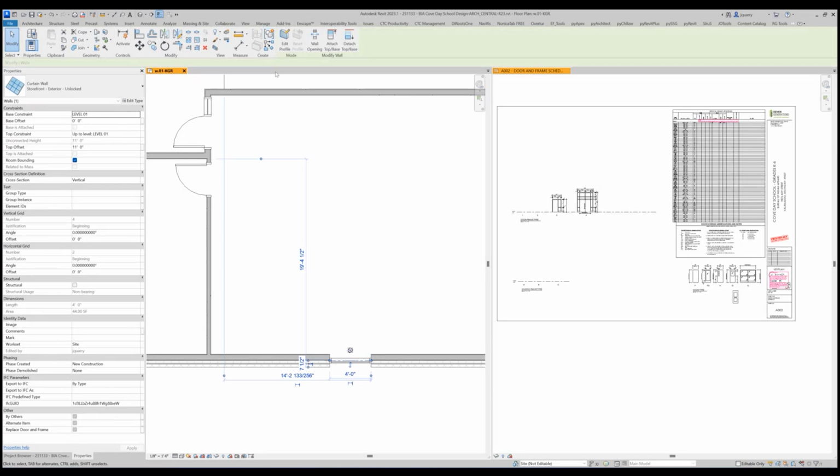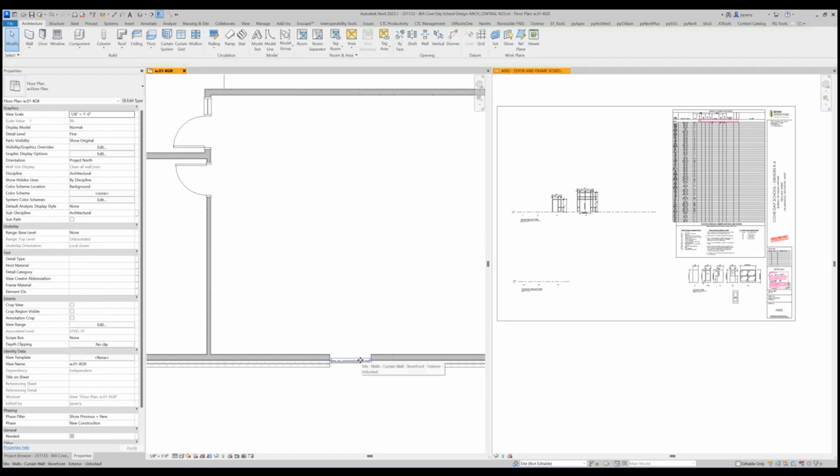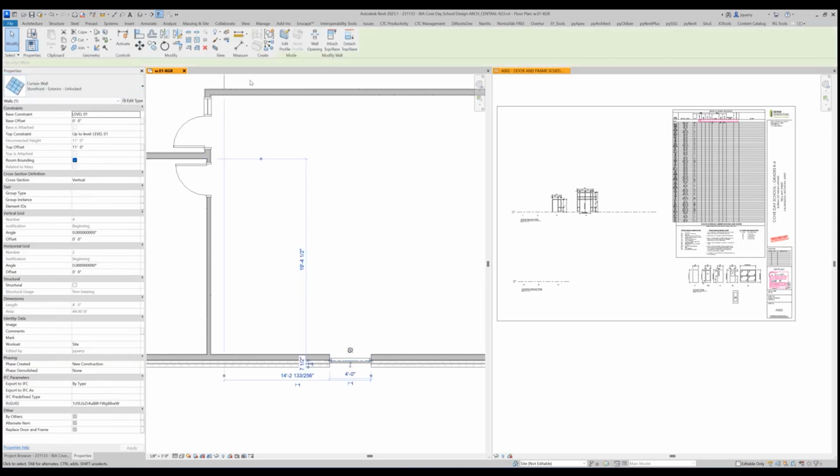Did you hit disallow twice? Yeah, I have to do one on each end. Oh, okay. Right click the dot, that's where it would join. Okay, that makes sense. Otherwise it'll join and change the length of your windows, which, if you have doors in it, will change your door widths and all kinds of fun stuff. Gotcha. All right, so this is an exterior unlocked. I'm gonna go ahead and group it. I'm gonna call this number C.